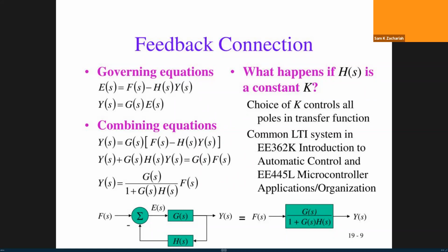You have studied the summing circuit using op-amp. Yes, sir. Now assume that this is a summer circuit, but the only thing is that an inverter is also placed prior to one of the summing inputs, so that this can be realized using an op-amp summing circuit with an inverter in the feedback path.